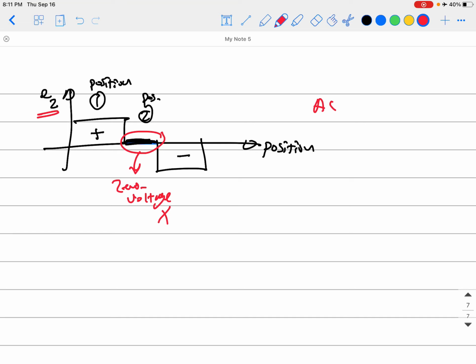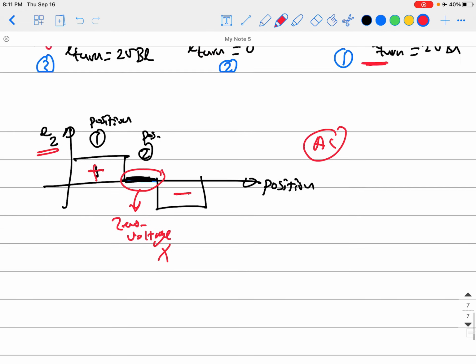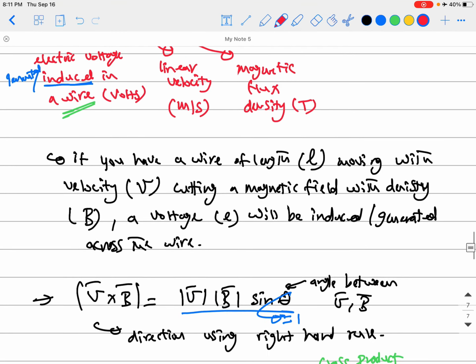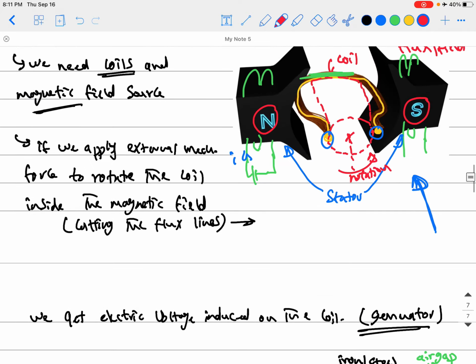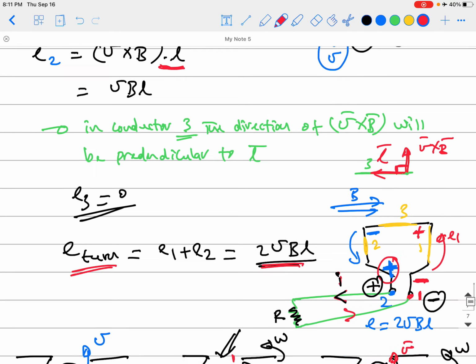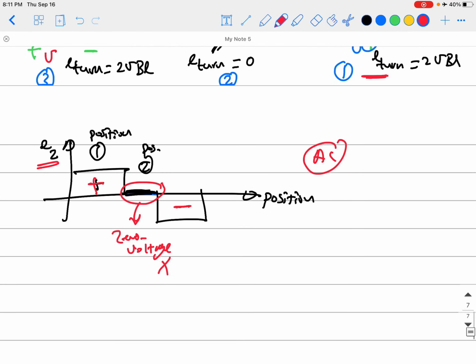The other thing is just looking like here, this voltage is AC. Remember we're talking about AC versus DC? Because you have a period that is positive and a period that's negative. And if we are trying to build a DC machine, like we said, we are talking here about a simple DC machine. That means the voltage we're trying to get out of this machine, we want it to be DC. So we don't like this to be AC. So those two problems we want to fix.